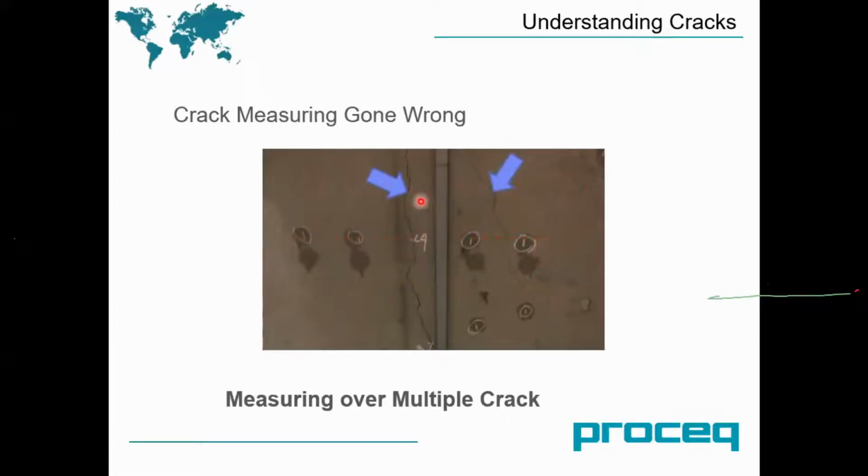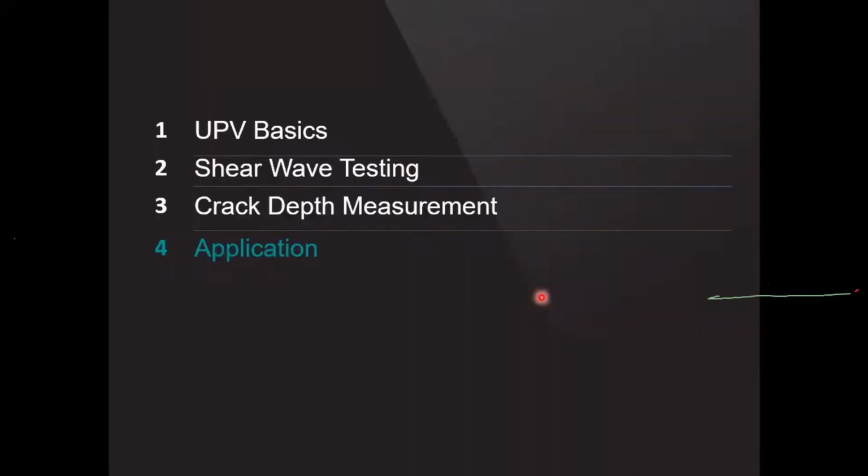And also, there's a crack here. The person doing the measurement, but you can see here, there's another crack, multiple cracks. So doing measurement across multiple cracks can also give you an error. So please take note of this as well, right?